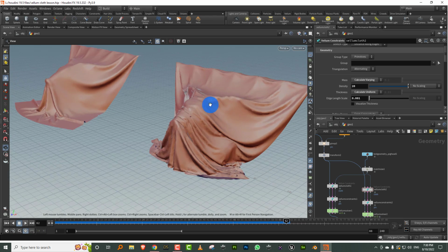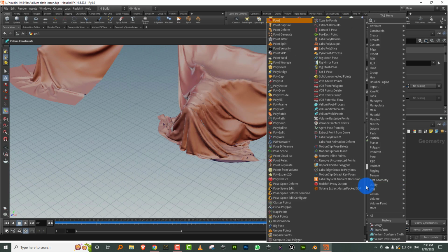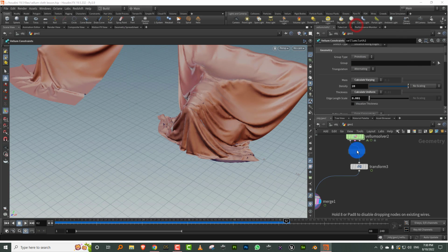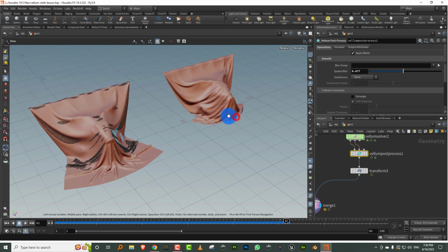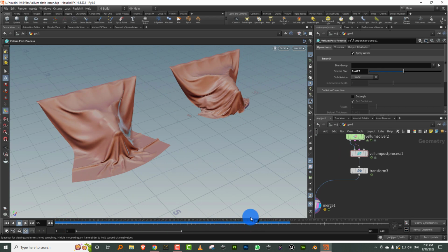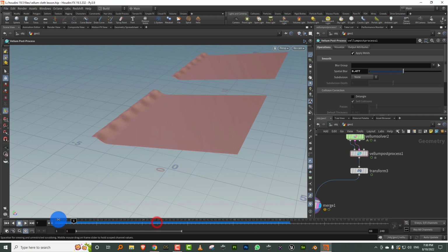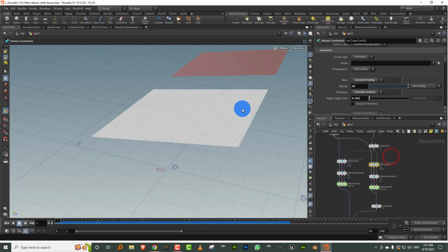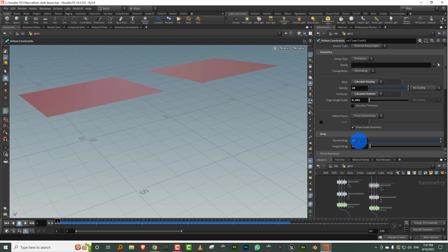Yeah, so you can do stuff. And if you're getting these, you can just apply a post process. Take a Vellum post process at the end, and I can give it a slight bit of spatial blur. That'll take care of it. There you go. See, it is still completely different from the default that you were getting before. Okay, let's get rid of this. So that's as far as the density, edge length scale and normal drag are concerned.